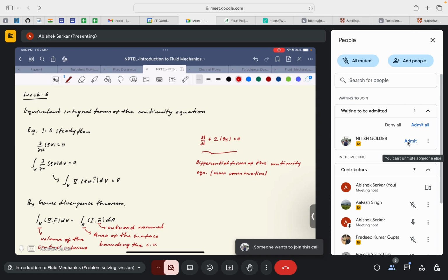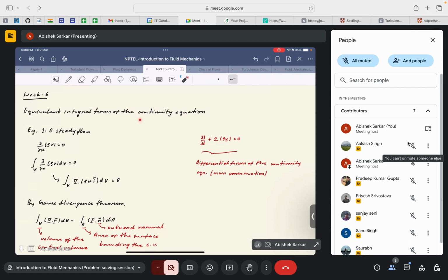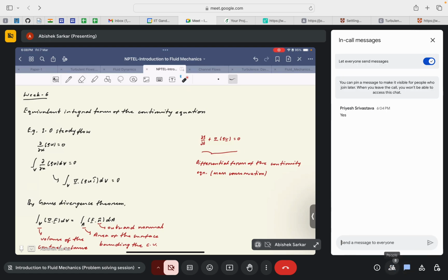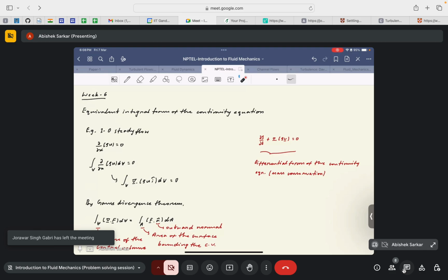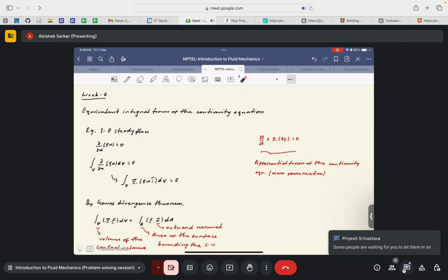So now we would like to look into the equivalent form of the governing equation of the continuity equation in an integral form. Why integral form? One of the key things to notice is that these conservation laws that we are looking into, say the mass conservation or the momentum conservation, are in terms of the control volume. Since we are looking into a control volume and a bulk property of the fluid over a definite area, the governing equations that we are eventually going to derive would be valid for a definite control volume, which would indeed comprise a volume integral.